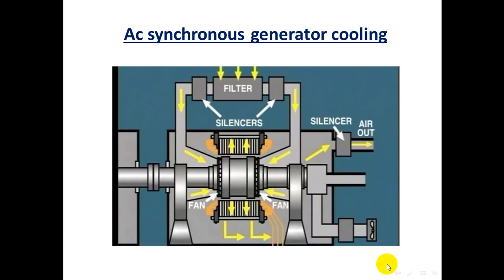In such cases, direct water cooling is used. In very large turbo generators, the rotor is direct hydrogen cooled and the stator winding is direct demineralized water cooled.